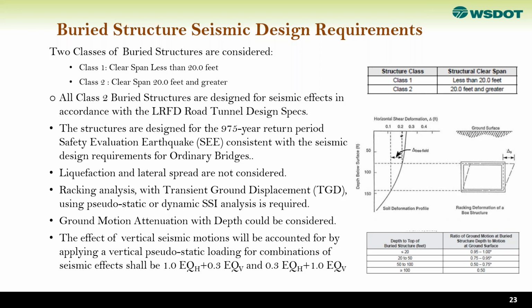And the seismic design is not covered in the AASHTO BDS or guide specification, so we borrowed that from the road tunnel design specification. The structures are designed based on a 975 years return period, similar to the bridges' 1000-year return period, and designed based on the safety evaluation earthquake, SEE, consistent with the ordinary bridge.